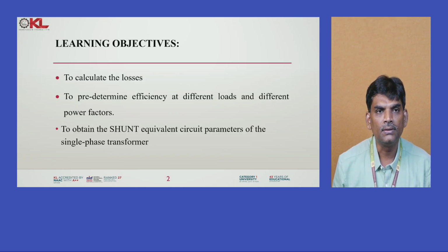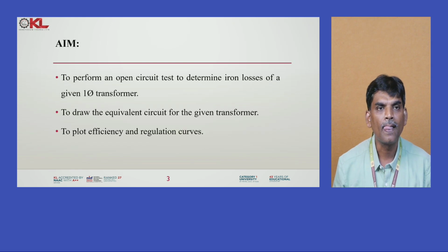So these are the learning objectives. The main purpose of the open circuit test is to calculate the iron losses and predetermine the efficiency at different loads and different power factors, and also to obtain the shunt equivalent circuit parameters of the single phase transformer.